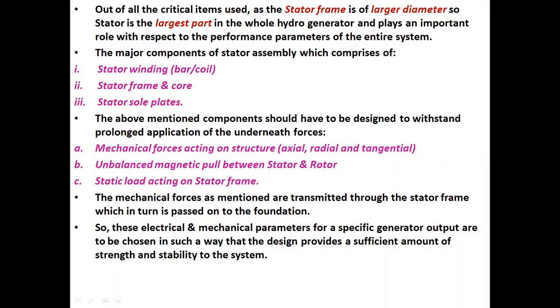A. Mechanical forces acting on the structure, that is axial, radial, and tangential. B. Unbalanced magnetic pull between rotor and the stator. C. Static load acting on stator frame. The mechanical forces, as mentioned, are transmitted through the stator frame, which in turn is passed onto the foundation.